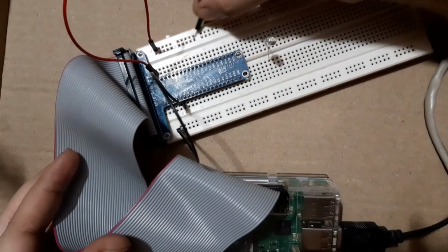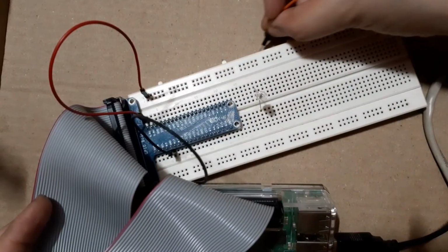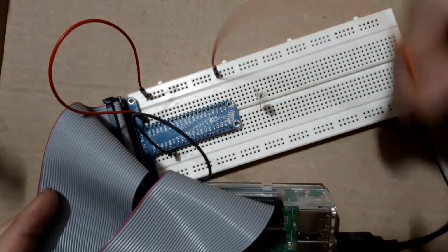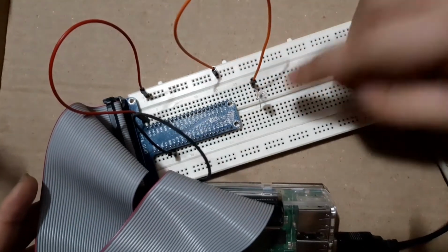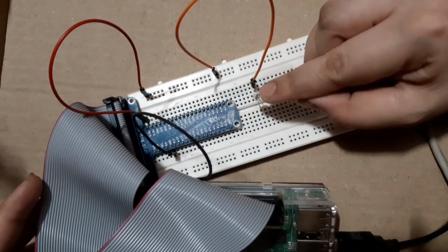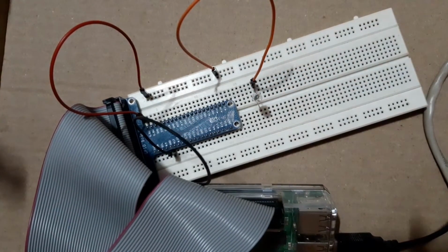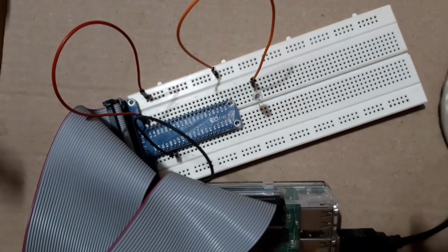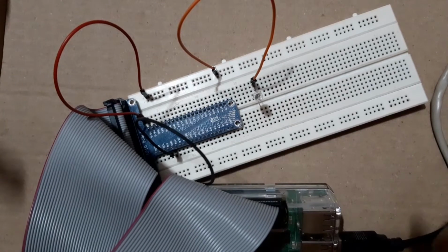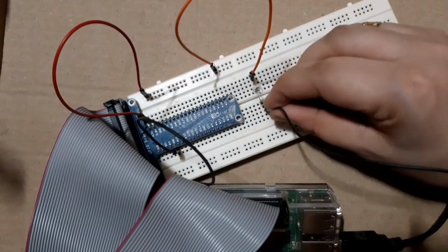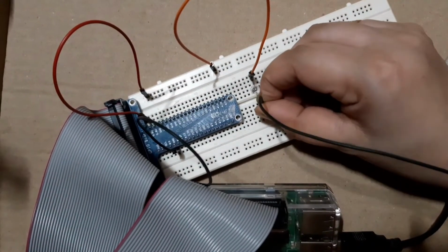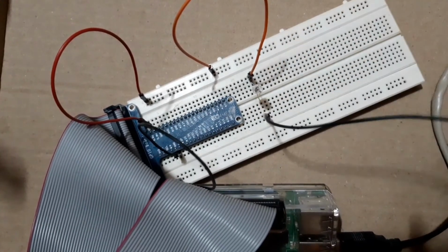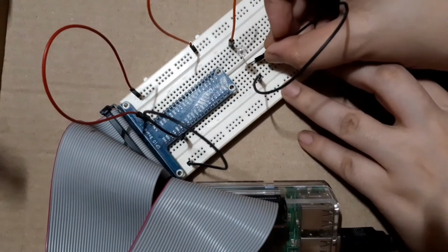Now you can insert this pin anywhere in this horizontal line, you'll get the positive of this, and this way you're giving positive to the LED. Similarly, if you want to connect the negative side or the ground of the LED, you can simply connect this here, because the LED's second terminal is in this line.